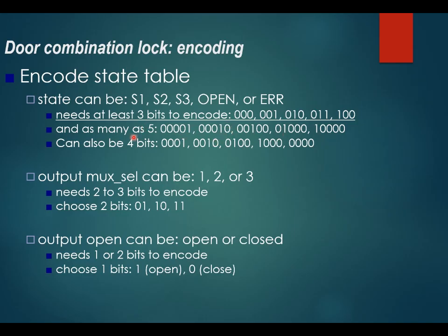So you can use one hot pattern to encode the state. Okay, so the first state is 00001, the second state is 00010. Or you can even use the one hot pattern plus the 0 to encode the states.